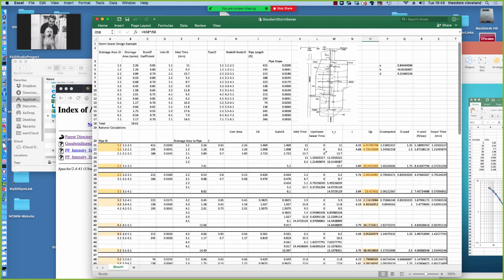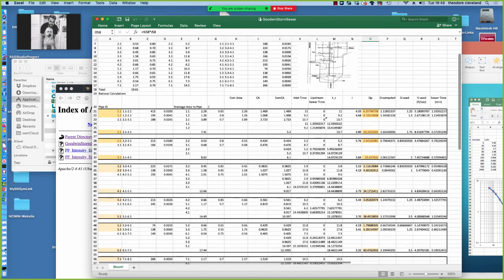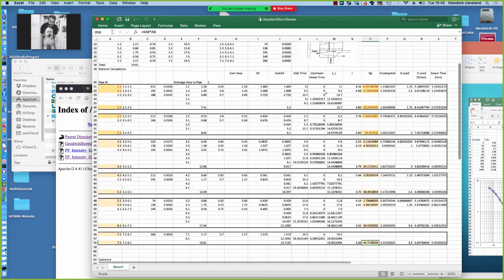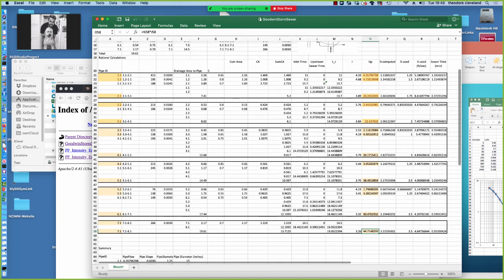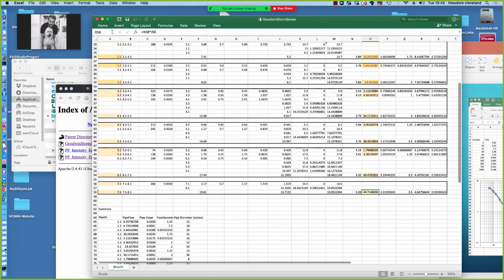So our total area runoff coefficient, regardless of how it's routing internally, is producing about the same expected peak discharge as our small area compositing. So that's reassuring. That means that we probably have not unintentionally lost some area somewhere.